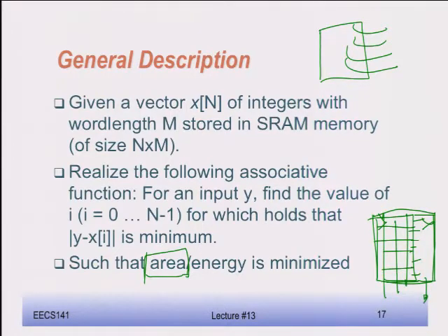Later on, when we do circuit optimization, we're going to be worrying a little bit about energy. But right now, forget about energy. We're just going to make sure that it gets the right function. So step 1 is going to be logic design. Design me something that does the right computations. How would you define the logic per cell, and how would you size the transistors in such a way that I get a decent delay? So we're going to do logical effort analysis, and you're going to size it in such a way to get optimal delay. But the logic and design itself is already going to be an interesting challenge.